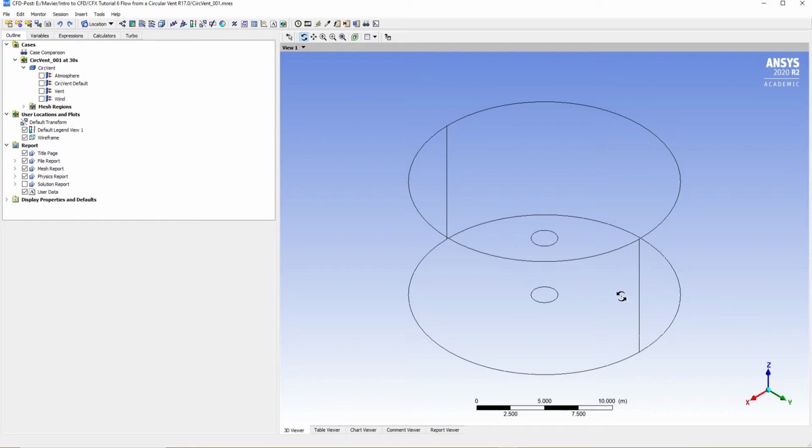How do you do this? Let's create an isosurface. An isosurface is basically a surface of constant value for a variable. For example, you could set up a surface consisting of all points where the velocity is, I don't know, 3 meters per second in your problem. But for this case, we're going to create an isosurface of smoke concentration, from the additional variable smoke that we set up earlier.